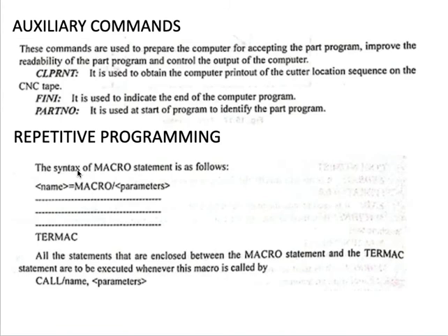And if you go to repetitive programming, the sequence of similar statements which need to be referred to more often in part programming are best referred to by a macro statement. This feature is similar to a subroutine in Fortran and other computer programming languages.